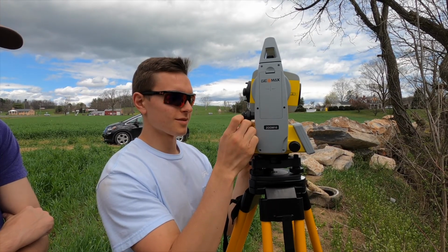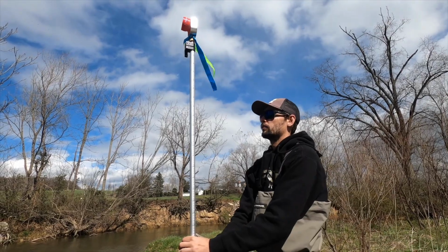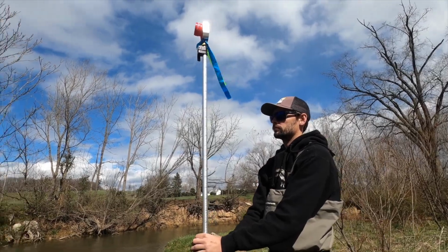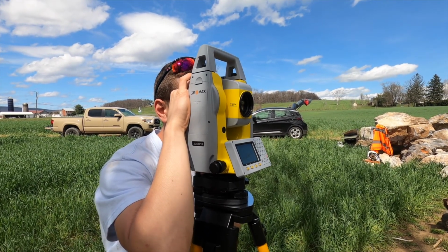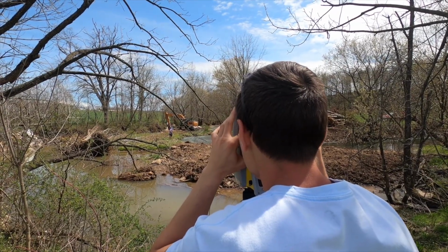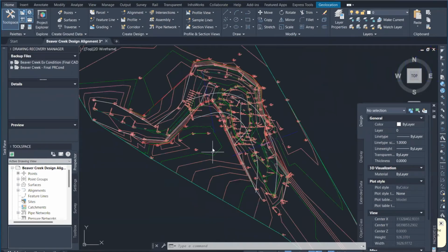The topographic survey combined points from both the cross-sectional area profile and the longitudinal profile survey, but also marked out a variety of key features throughout the stream, such as the island, the thalweg, and both banks of our stream. These points were utilized in our CAD design, which was used to create our final design.